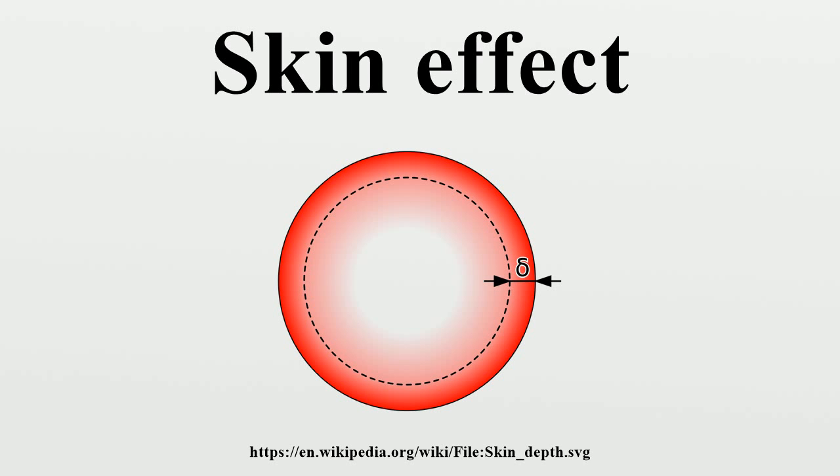In a single wire, the internal inductance becomes of little significance when the wire is much longer than its diameter. The presence of a second conductor in the case of a transmission line requires a different treatment, as is discussed below. Due to the skin effect, at high frequencies the internal inductance of a wire vanishes, as can be seen in the case of a telephone twisted pair below. In normal cases, the effect of internal inductance is ignored in the design of coils or calculating the properties of microstrips. Inductance per length in a coaxial cable.